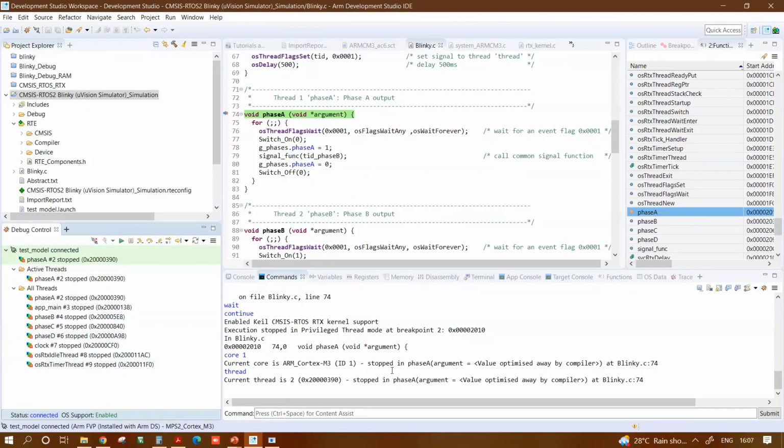The idle thread is for when none of the tasks are executing. Instead of wasting time, the processor gets into the idle thread. Here, if you want to reduce the power consumption of your overall application, you can put the processor into sleep mode. The task switching happens from one task to another when the system timer overflows, which is nothing but an interrupt. Once the processor gets a system timer interrupt, it wakes up from sleep mode, thereby reducing the power consumption of your application. Just giving an example. Any code you want the processor to run in the idle thread, you can put it. It's an editable function. You can do that.